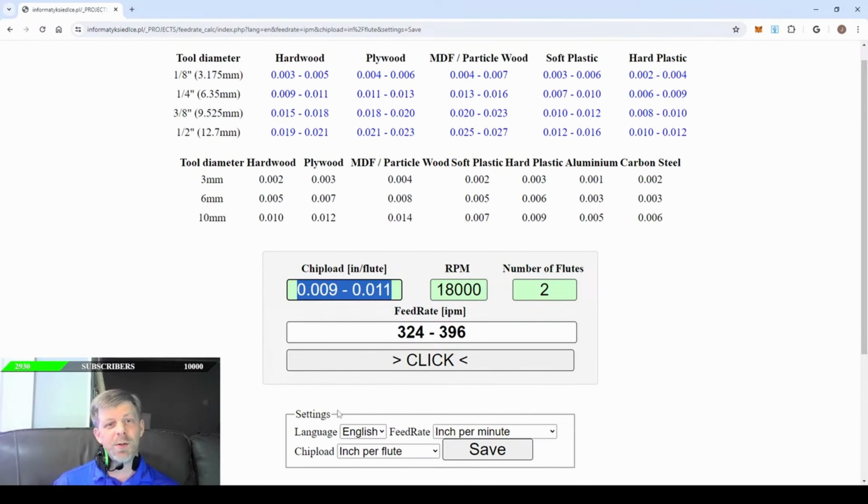And the number that I've figured out is really 0.002. And this is sort of where the high-end hobby style CNC machines will begin, at about 0.002 less than this chip load. The further down the hobby CNC range, where you get into your mid-range hobby CNCs and then your desktop hobby CNCs, you're going to want to reduce this by 0.003 or maybe even 0.004.